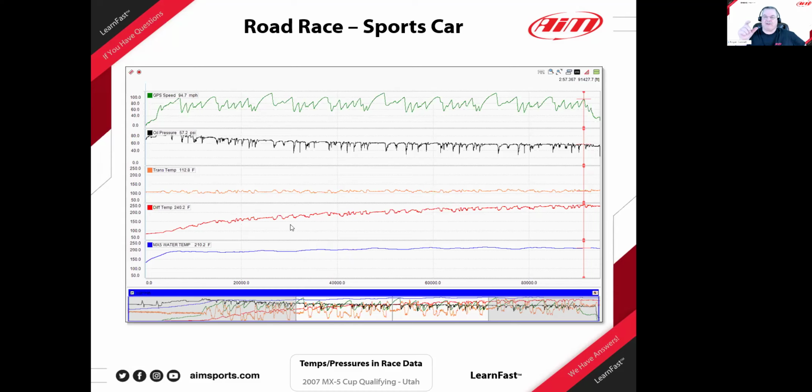We had put in some very, very thin transmission and diff fluids to try to get performance, and it did work. The car gained lap time by quite a bit. But look at the temperature of the rear differential and what it did over the course of just a warm-up lap, a fairly easy warm-up lap, 2 hot laps, and then coming in. It started at 75, 50 to 100, 75 or so degrees surface temperature, normal temperature.